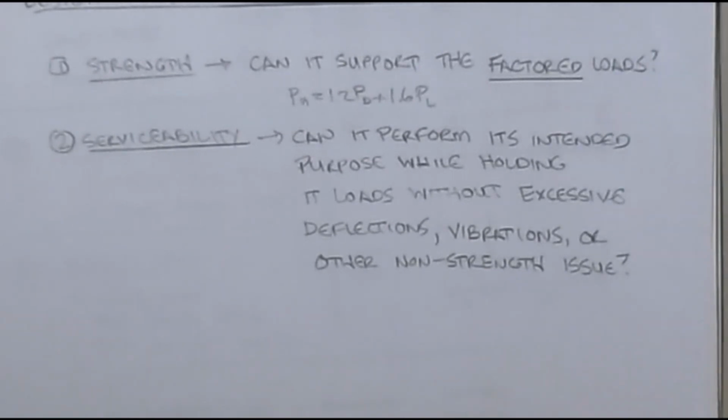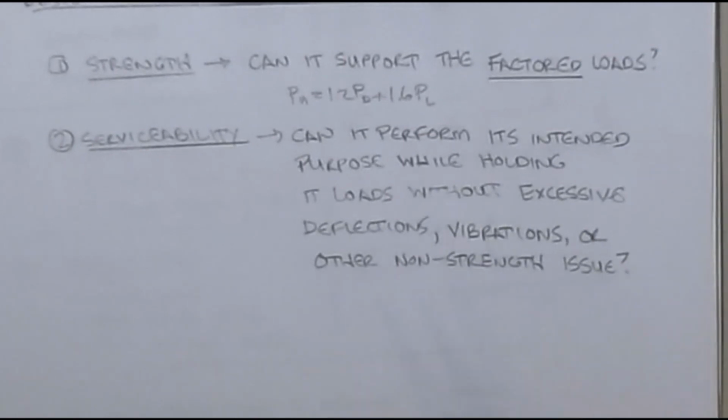For serviceability, it's different. We don't factor the loads. What we do is we use the service loads, or an unfactored load case. So we've got to be very, very mindful of that.